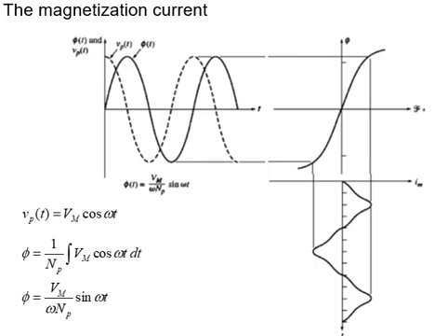Since there is a cos omega t, for t equal to 0, cos omega t would become 1 and Vp(t) would become Vm. So as you can see from the first figure, Vp(t) starts from some amplitude Vm at t equal to 0.